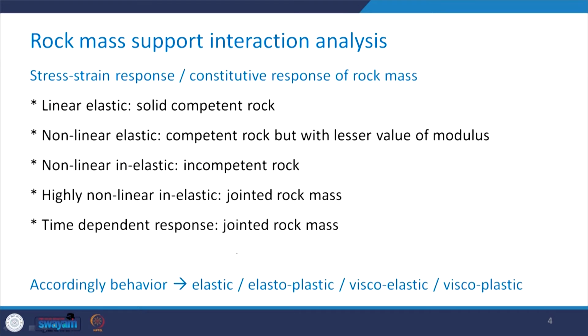Coming first to the stress strain response, or the constitutive response, of rock mass. We had a dedicated chapter in this course on this topic. We saw that the constitutive response can be linear elastic, and that would be in case of solid competent rock. It can be nonlinear elastic in case of competent rock but with a lesser value of the modulus.